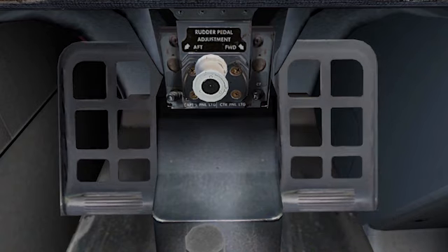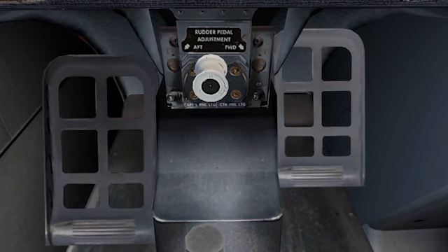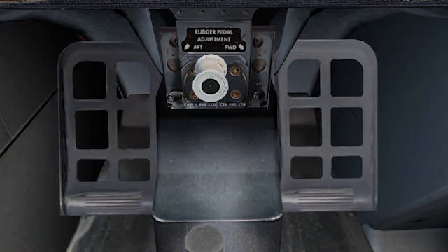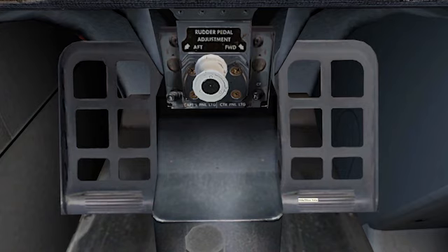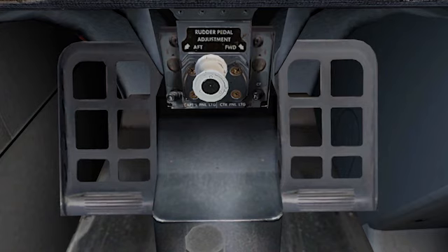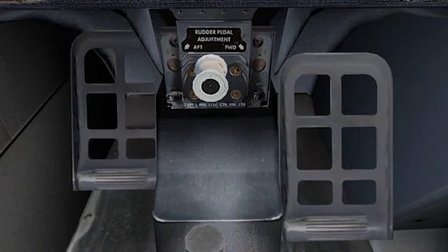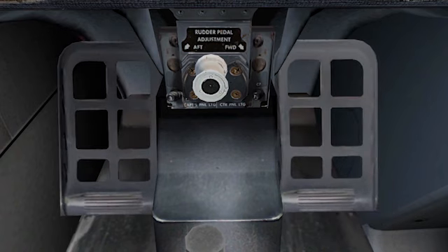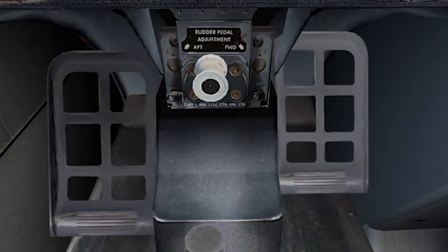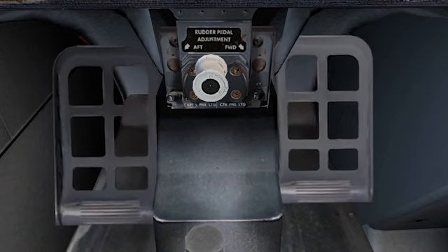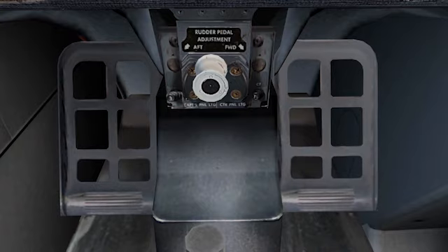The rudder feel and centering unit gives simulated feel to the rudder pedals and centers the rudder and rudder trim inputs in the rudder PCU. When a pilot presses his rudder pedals, a roller is moved and springs are compressed, supplying feel force to the pedals. When the pedals are released, the roller moves to a detent and the system moves to a neutral position.